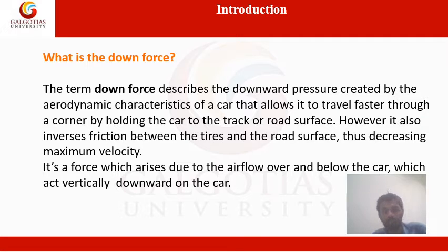So it's a force, in other words, which arises due to the airflow over and below the car, and acts vertically downwards on the car. I would like to tell more about the downforce. Downforce is the downwards lift force which is created by the aerodynamic characteristics of a vehicle.